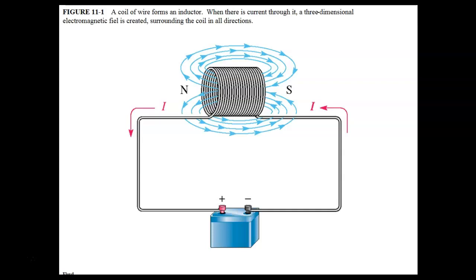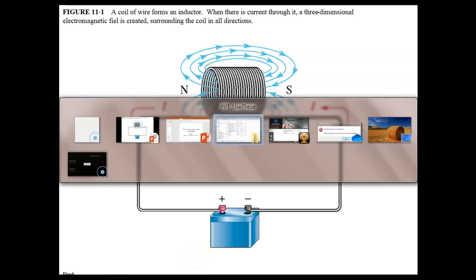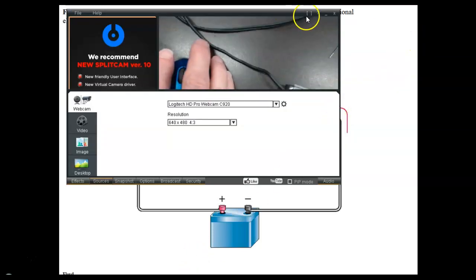So we should be able to check these things with an ohm meter. If you check these with an ohm meter, they all measure infinity, so that means they're open. What happens with these is that we don't like to really use these because the wires are so small, and if you look real close, you can see where they are attached.